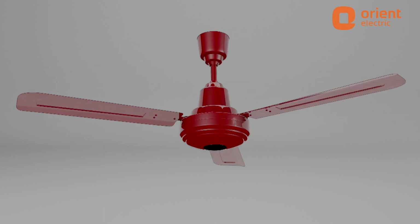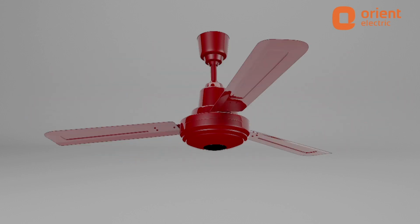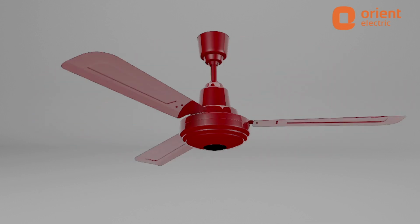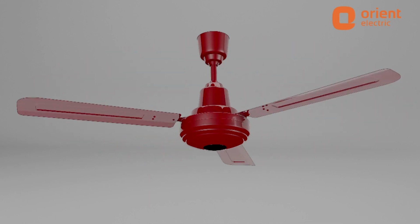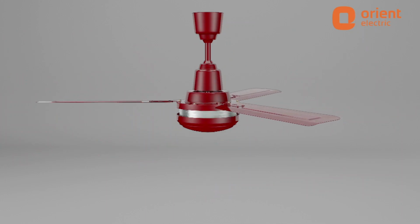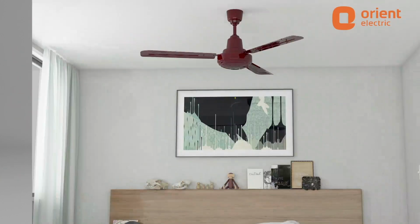Sometimes a fan makes humming noise only when it's running on inverter power. And if that is the case, explain the same to the customer. If the humming sound is not due to any of the reasons mentioned before, the fan stator could be defective, in which case you will have to replace it. Low speed or low air breeze.